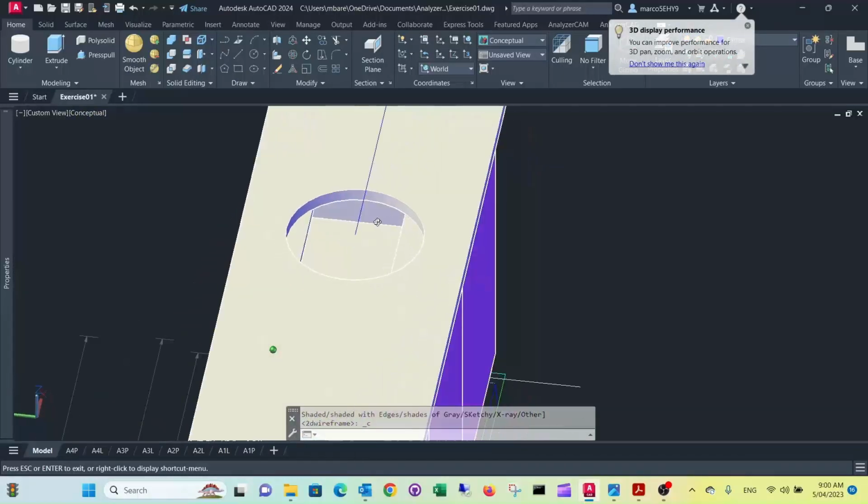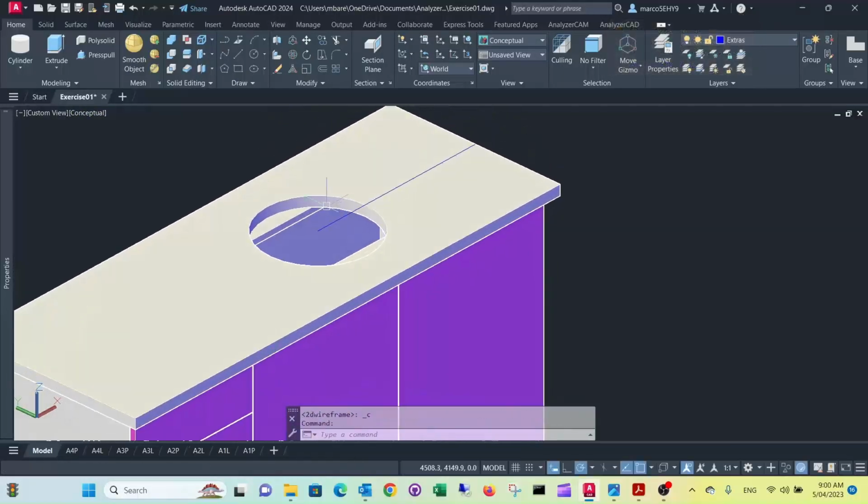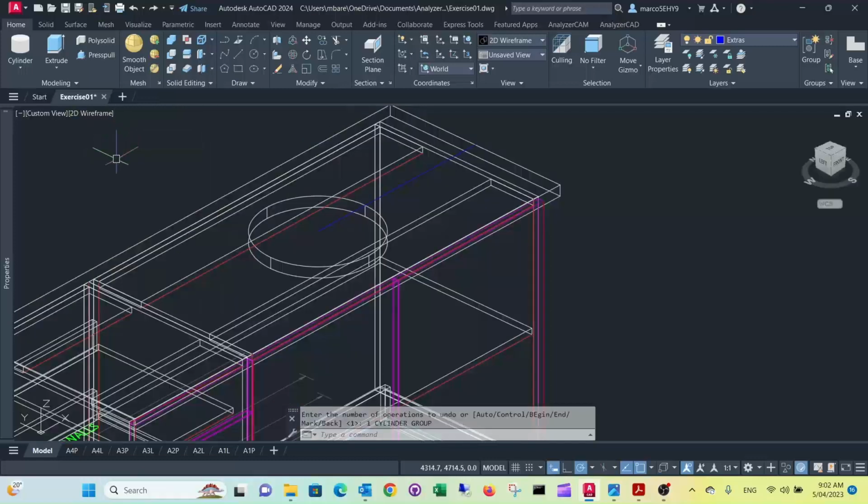Now there's only one little problem. The top rails, they're actually going through, so we can also automatically cut them out in a round shape. Now we want to make those cutouts slightly bigger than the cutout on the bench top, so that allows for tolerances in your bench top.